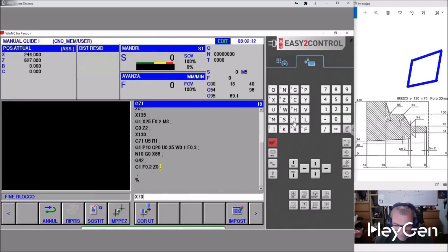Now, I don't recall if we perhaps need a comma, so let's put it in and see. C2 and EOB, insert. Z-20, R4. Then we have an angle of 60, so 180. Angle 120, 100, R6, and I'm here, so angle 120, R6, I stop at X100.